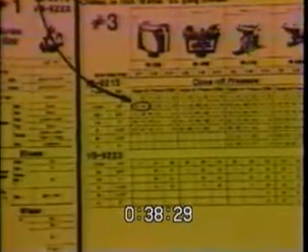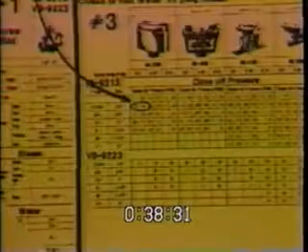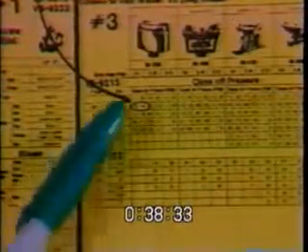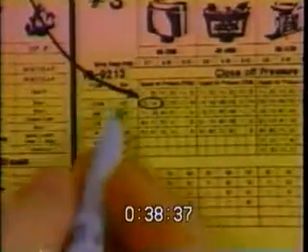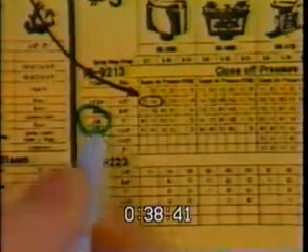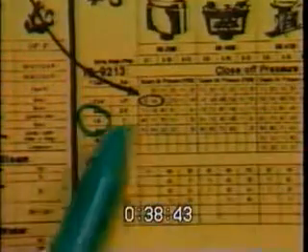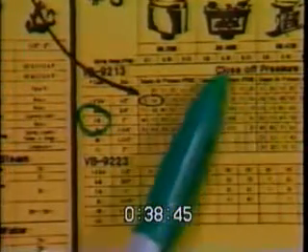Once you've determined what type of valve to use and the port code, the third thing is to choose an actuator. Now the actuator sections are divided into 3: pneumatic, electronic, and electric. Here we have the pneumatic section, and we're going to take a look at our valve. In this case, it was a 9213-7, which is right here. All these ratings that you see, all these little numbers, is the close-off pressure rating.